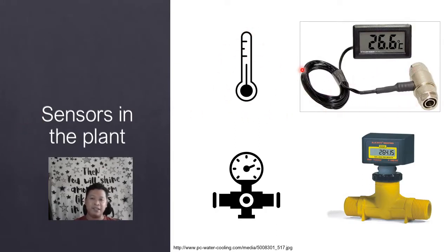These are usually inline sensors. For example, in continuous processes, you have an instantaneous temperature measurement device for the product flowing through a tube. And at the same time, you would need to measure, for example, their flow rate to know how fast you're producing things and to adjust the other parameters such as the rate of heating and for other things that could affect product quality and safety.